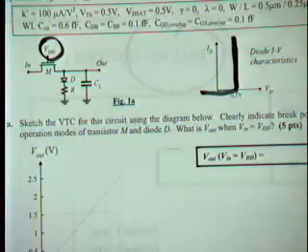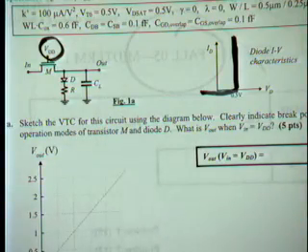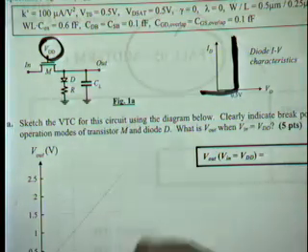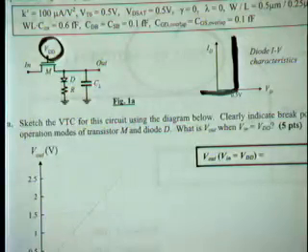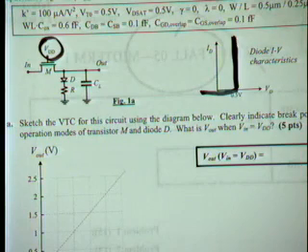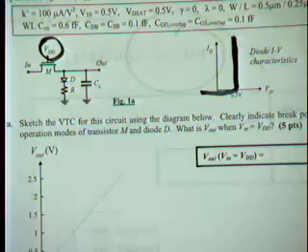You solve the thing, and then you might end up with something that looks totally nonsensical. If it doesn't make sense, you probably made the wrong assumption. Go back and say, okay, wait a second, I made the wrong assumption. Maybe the diode is off. That's the way you deal with nonlinear networks. You make an assumption, you find the operational region, you solve the network for that operational region, and then you reflect on the result that you get. The reflection says, well, the voltage that I'm getting at the output is higher than the supply voltage. You know you're going to have a problem. If you have something like minus 10,000 volts, you know you have a problem. So that's what you should do in this case.